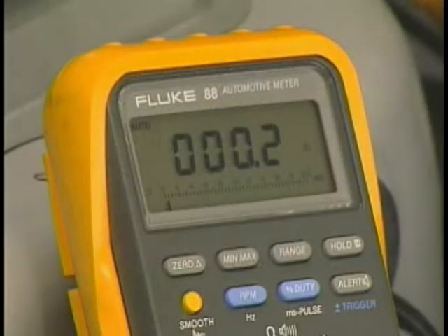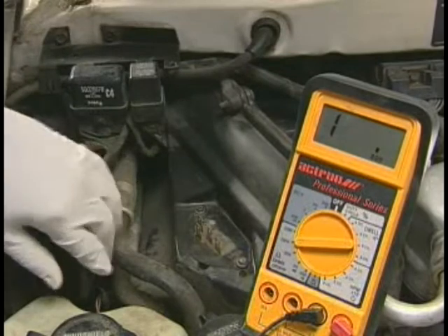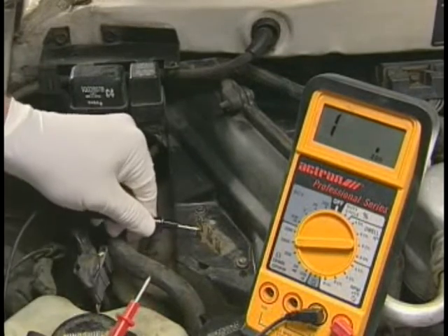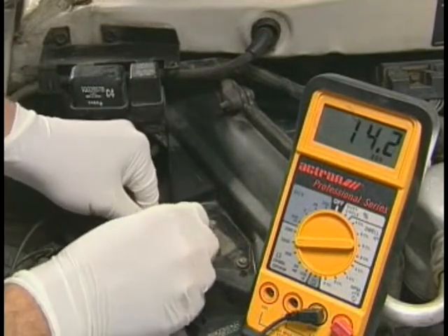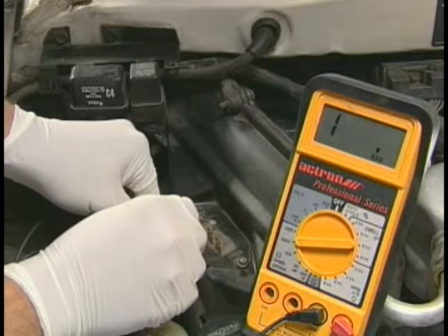Multimeters can be used to check for current. Voltage drop tests are useful to find excessive resistance that will cause diminished or no operation of components. The ohm meter function of the multimeter is used to check resistance of components. Always remove the fuse on circuits prior to using an ohm meter, or the meter may be damaged.